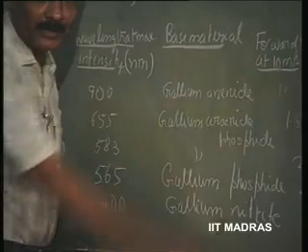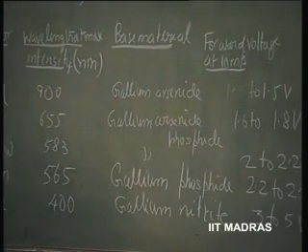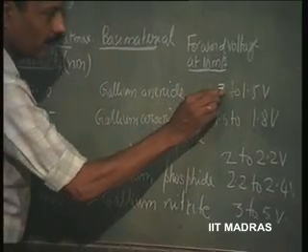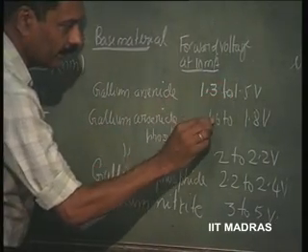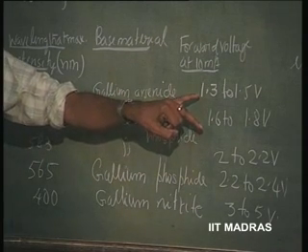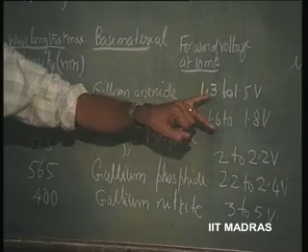if sufficient forward current is applied, typically 10 milliamperes or so, and the typical forward bias voltage. Now, please compare this with the forward bias voltage of a silicon diode, which is of the order of 0.5 to 0.7 V, we said, at currents of the order of milliamperes. Gradually it might become 0.8 to 1 V as it goes to higher currents. But here it is greater than 1 V, for 10 milliamperes itself, 1.5 volts.